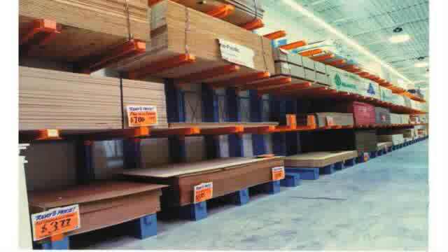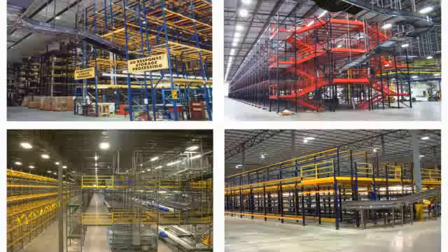This slide here basically shows what they would call a heavy-duty cantilever rack. But there are lighter forms of cantilever rack, and one of the best examples is for furniture storage in warehouses, where you have a lot of irregular shapes. You would lose a lot of space if you tried to put these things into a selective rack, because it's kind of hard to match the product up with the shelf size. And like I said, that's one of the most common applications for a light-duty cantilever rack.